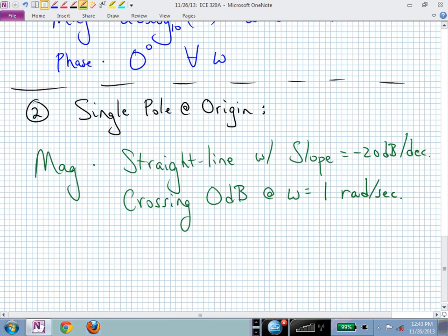It's not going to break there. It's going to just pass through there because its slope is always minus 20 dB per decade. So its value is really big at low frequencies. Its value is really small at high frequencies. That's its magnitude. So it's always on, it's always sloping, it's never going to break. That's important because a lot of people want it to break at 1. That's just where we're locating it or using it to locate.